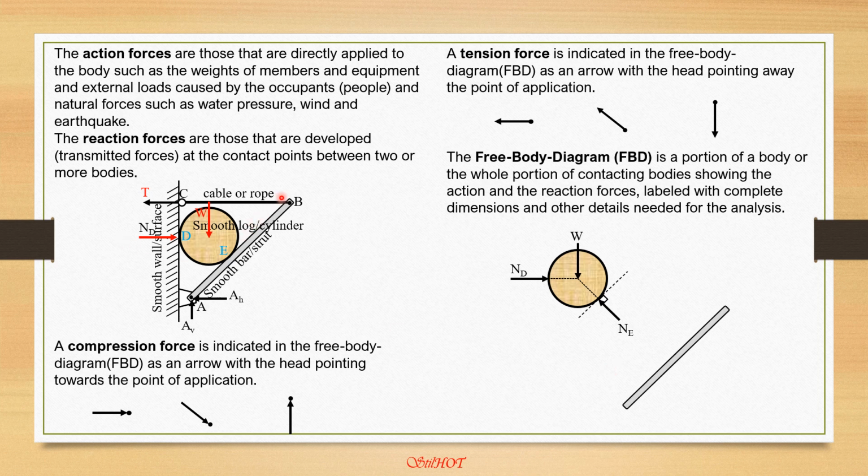Then if we draw the free body diagram of the lug, by the way, for the external reactions, the direction of the external reactions will not change. Only the internal reaction will change, from axiom number 4. Because NE is an internal reaction, remember action and reaction forces are equal but oppositely directed. So if it is up to the left on one body, on the next body it is down to the right.